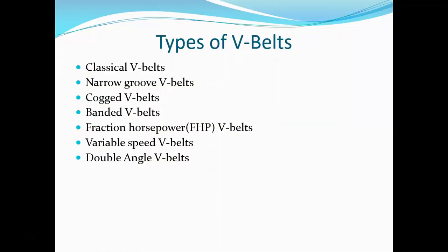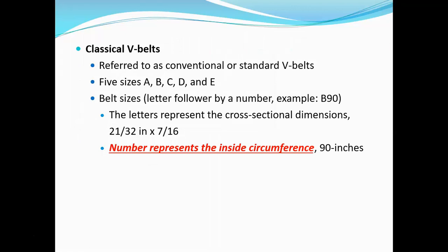All right, now belt drives in this section, the hardest thing to remember for the test is going to be the sizing. Each type of belt has a different sizing method. You would think that they'd try to standardize that, but they did not. So it doesn't make sense how the classical V-belts are sized and how narrow groove V-belts are sized. They're totally different. So keeping up with that is going to be the hardest part. Other than that, V-belts and timing belts are fairly simple drive devices.